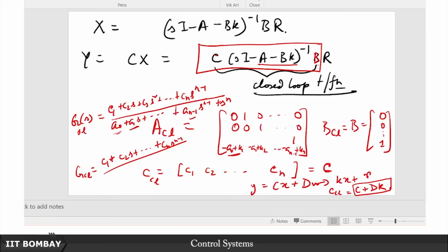So if you have a right half plane zero, well, tough luck, it seems like there is nothing much you can do independently. Once you have chosen your K to assign your poles, you have to live with whatever zeros come as a combined package with it. You cannot reassign them independent of the pole locations, right. So that is one slight catch which we cannot address using linear time invariant control action.